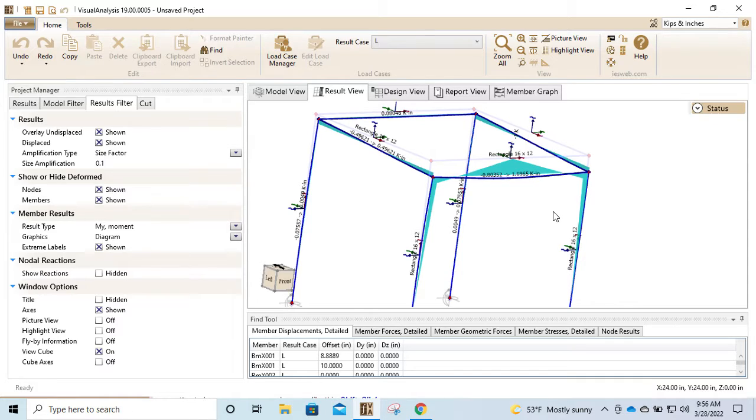So we're using a variational beam and making an assumption. Do you use plane stress or plane strain? You will be using the variational beam element that also incorporates axial load, right? Because that uniform load W is acting in the global Y direction, that's acting in two local coordinates. So I gave you the shape functions and the matrices, it's all in the notes for how that works. The derivation is the exact same as the axial load.